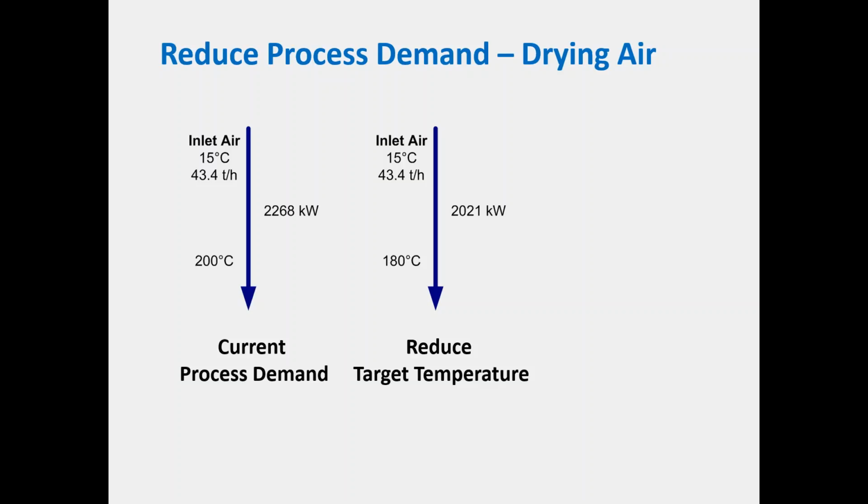Now that may or may not be possible. It really depends on the process. Often when you change temperatures, there are some other effects that go on, such as quality and things like that, yields, for example. But that may be an option. Do you actually need to heat your streams to the temperatures which they are currently being heated to?